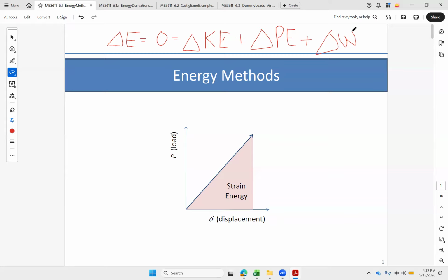So we pull on something with additional load, it'll stretch out farther and farther along that elastic slope, right? And the area underneath this curve is our strain energy. That goes toward this potential energy. It's a stored or strain type energy, all right? So force by displacement, we go up that curve to some applied loading, and we've displaced a certain amount. Here's the energy that we're holding. Force on one axis, displacement on the other. So the area under this curve is an energy value.